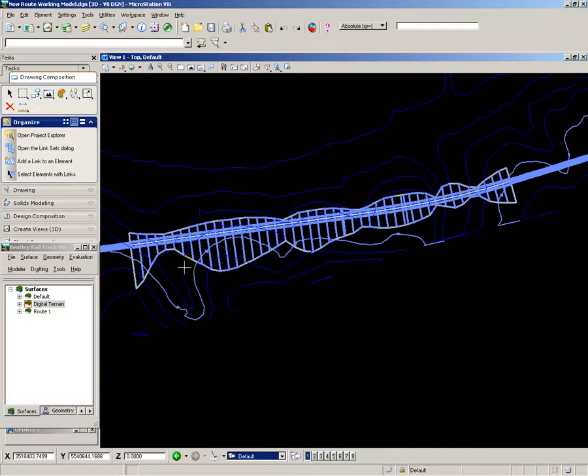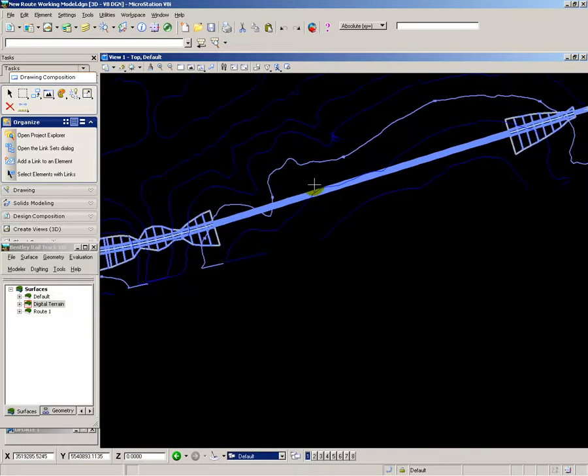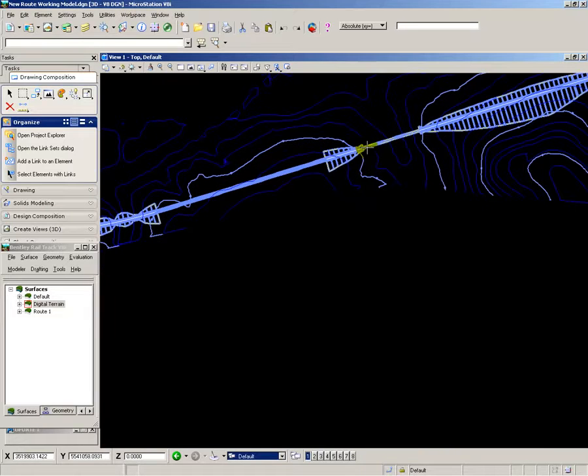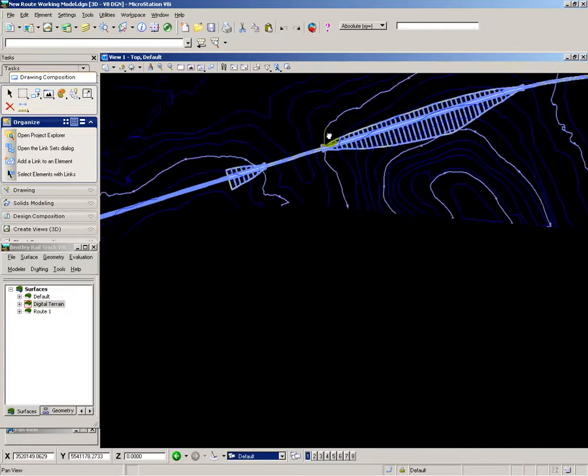Quite heavy earthworks here where it's sidelong ground causes difficulty on this side. Perhaps start considering either retaining walls or moving slightly out of this slope. Into tunnel through this section. Now here clearly by realigning through this area here it would be possible to avoid that tunnel altogether, keeping close into the hillside, but it would necessitate a slightly longer viaduct here.